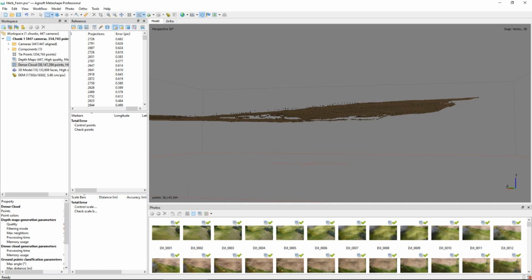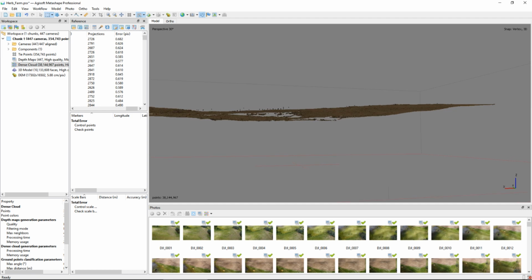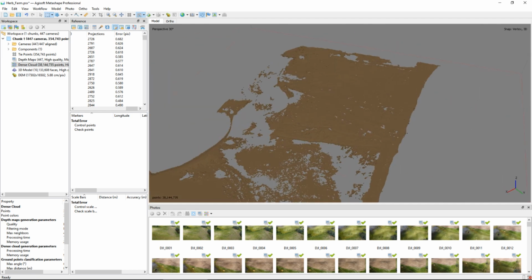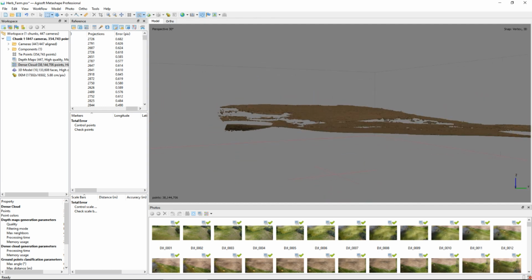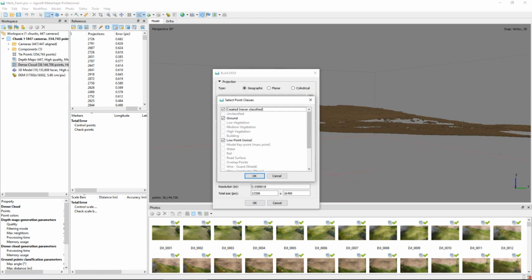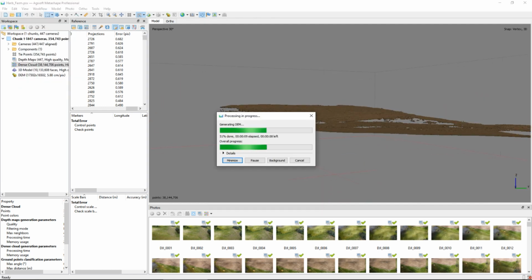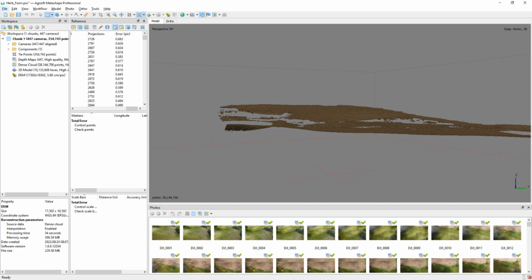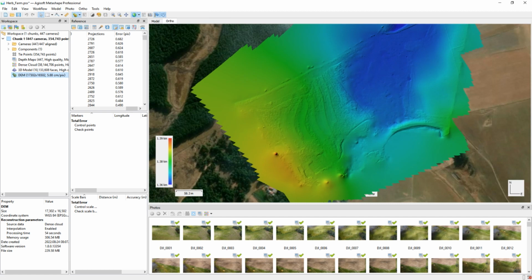Take your time to do this carefully, not quickly, as you see in the video. Now we can recreate the digital elevation model and observe the result. In this case, apart from one spike, we almost have an optimal digital terrain model. For the sake of the video, I shan't clean out that erroneous point, but we'll move on to the next step, which is creating contours.